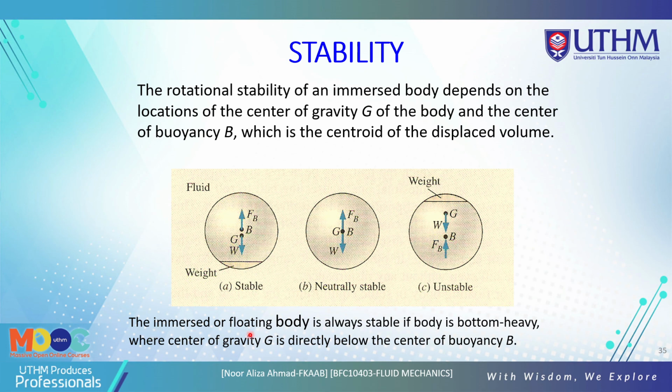Okay, so the image of a floating body is always stable if the body is bottom heavy, where the center of gravity G is directly below the center of buoyancy B. So maybe the G is below the B. So this is stable.